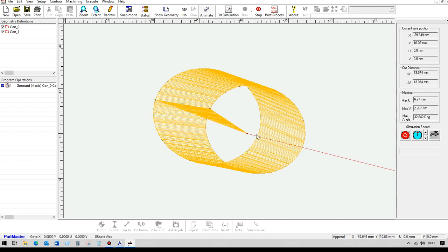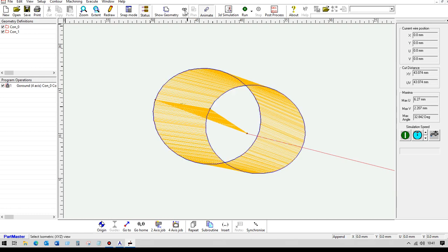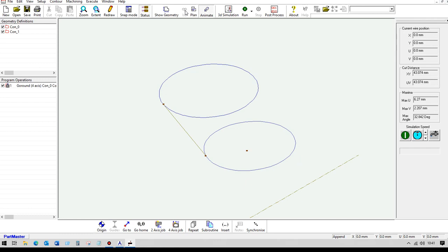Now in this case the pilot hole position I've set as 5 mm, but you can adjust this to a known position. Note also that the start hole position, the pilot hole position, will need to be somewhere where it can be addressed vertically. Otherwise how are you going to drill it? I suppose you could drill it on an angle. That's one way of doing it.